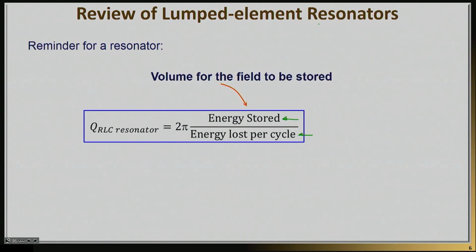Now, in order to build such a good quality resonator, it is important to understand physically where energy is stored and where power is lost. So energy is always stored in the volume that you're storing your electric and magnetic field. So the larger you can make that volume, the better things are. And that's why typically physically large resonators tend to have higher Qs than small resonators. And that's why distributed resonators, cavity resonators, or transmission line resonators have better quality factors than lumped element resonators, because lumped elements are by definition tiny, small.